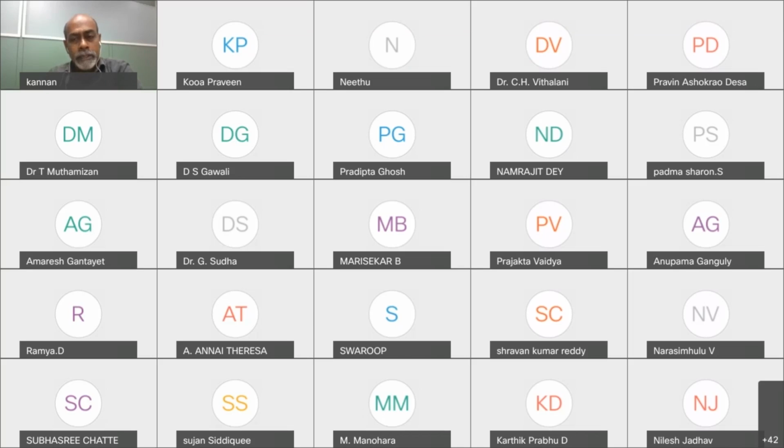So later on, when the driver chooses any current, the software will look in that lookup table and match the angle for that particular current and supply the angle. This is how the software works. What is called the MTPA algorithm.